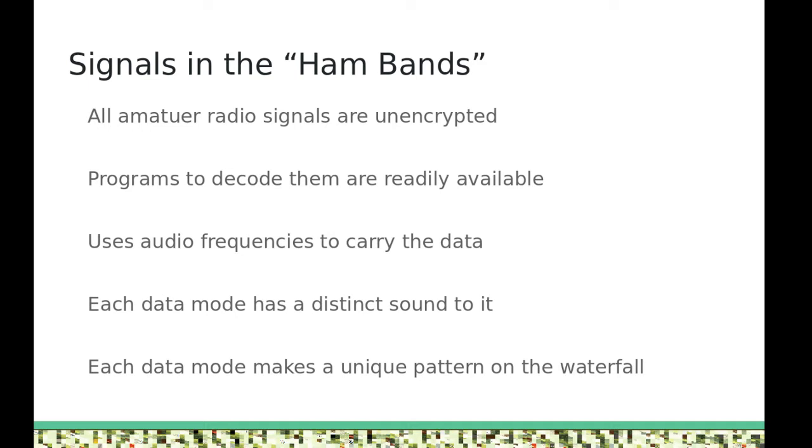And then each mode has a distinct sound to it. Just like you can tell the difference between my voice, your mother's voice, your best friend's voice, you can tell what digital signal is just by the sound. Of course, you're going to have to practice with that. You have to go out there and listen to different things, but eventually you know what PSK sounds like, you know what RTTY sounds like, you know what SSTV sounds like. And they're all very distinctly different from one another. And then also you're going to look at the pattern on your waterfall for each digital mode. That's going to be unique. It's like a fingerprint.